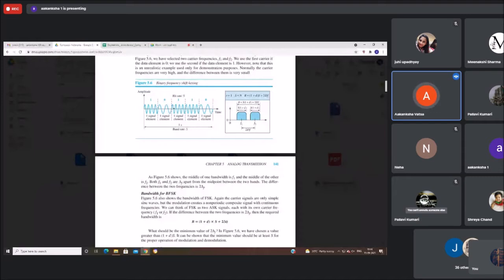तो जिस फेज में पॉजिटिव या नेगेटिव फेज में आपकी साइन वेव चल रही थी, उसी फेज में उसने नेक्स्ट सिग्नल को कंटिन्यू किया था. So this was continuous, but sometimes it is not continuous. So when one signal element ends and the next begins, there is discontinuity. So in coherent BFSK, the phase continues to the boundary of two signal elements.